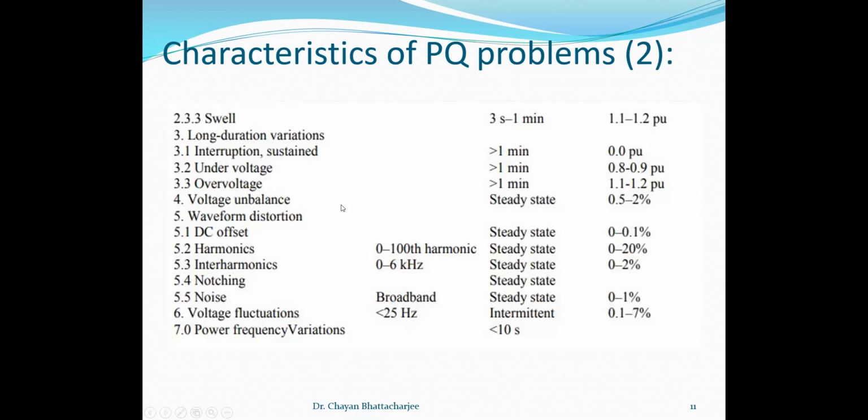As you know, in an unbalanced system, three phase sequences are possible: positive sequence, negative sequence, and zero sequence. The positive and negative sequence phasors rotate in opposite directions, and these two currents actually flow through the power lines. The zero sequence currents are co-phasor, so they are actually ground currents. They flow into the neutral and into the ground.